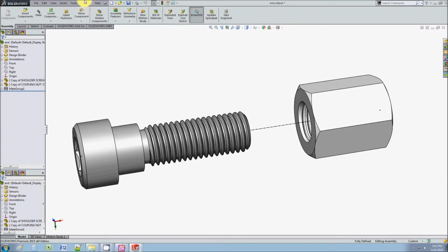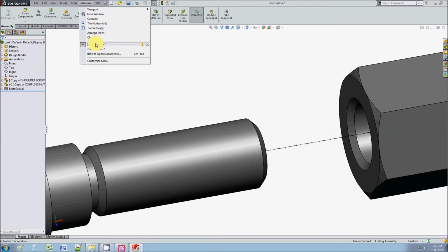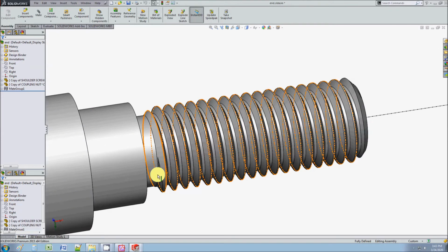Couple of things I want you to notice. Did you notice this chamfer here on the ends? See this chamfer? This is really good because when you do that, you get a really clean exit on the threads, as you see here. Same with the other end. It's a very clean exit. Otherwise, you'll see it just stop arbitrarily in the middle of nowhere, and it's not going to be clean. To fix that, you can actually create another sweep, another spiral with a draft angle, and as it fades off, it gives you that same effect. That's only if you don't have a chamfer. But personally, I find it much easier to just include a chamfer to achieve that really clean exit on the thread.